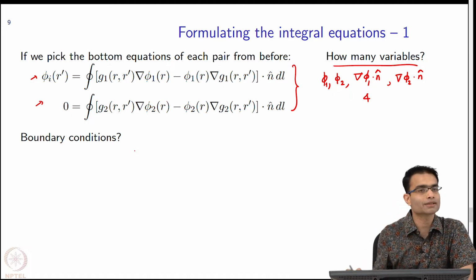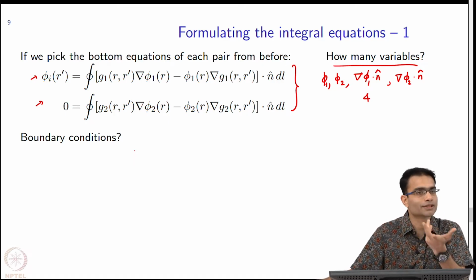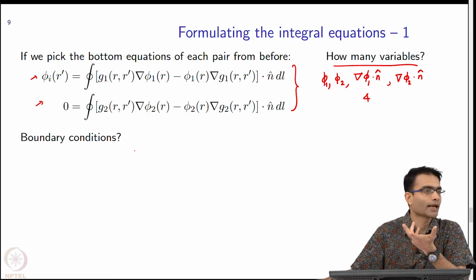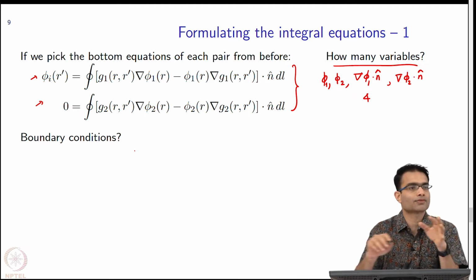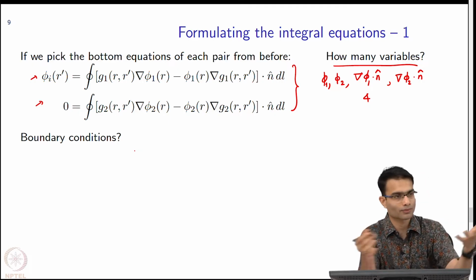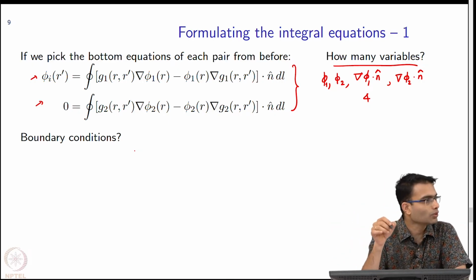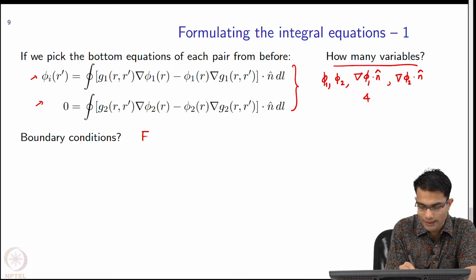So, what are the boundary conditions that we have studied in electromagnetics? Simple boundary conditions. Tangential E fields are conserved, tangential H fields are conserved as long as there are no pure surface currents. In this problem there are no pure surface currents because I did not say that it was a pure metallic object or something, it was some dielectric object, like a piece of wood or whatever. So, I know that physically there are no surface currents. So, E tan is equal to E tan 1, let us write it.